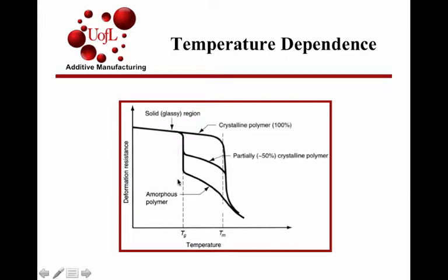It goes through a transition which is referred to as a glass transition, Tg. Then it continues to go through a decline, but you have an amorphous or a rubbery phase, and then you go through the final fluid stage to make different shapes. A fully crystalline polymer, on the other hand, would at a much higher temperature go through a sharp melting transition that is shown over here, after which it turns into a melt.